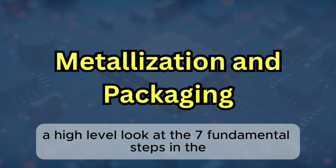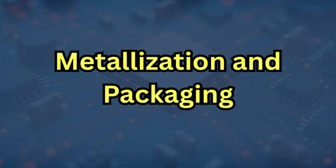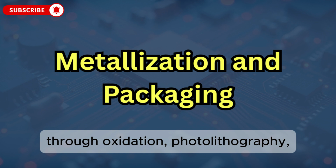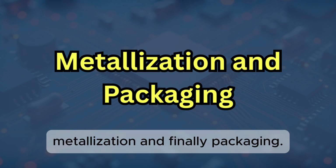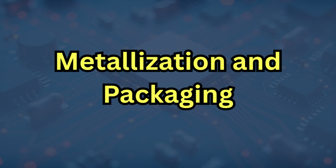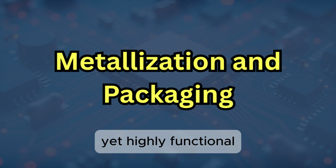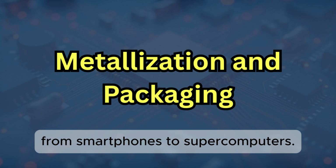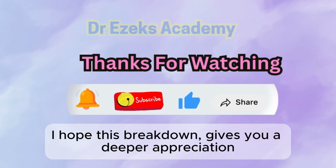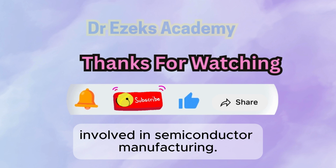And there you have it. A high-level look at the 7 fundamental steps in the IC fabrication process, from wafer preparation, through oxidation, photolithography, doping, etching, deposition and planarization, metallization, and finally packaging. Each of these steps is essential in producing the highly complex, yet highly functional integrated circuits that power everything from smartphones to supercomputers. I hope this breakdown gives you a deeper appreciation of the advanced techniques involved in semiconductor manufacturing.